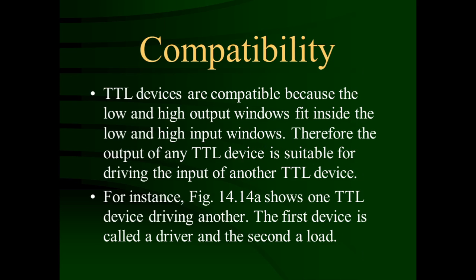The next important thing is compatibility. What is the meaning of compatibility? Compatibility means the output of any TTL device is connected to the input of any other TTL device. Can we connect directly without any buffer stage or anything else? Then it is called compatible.